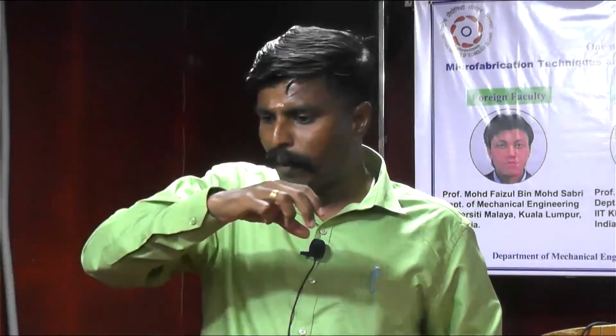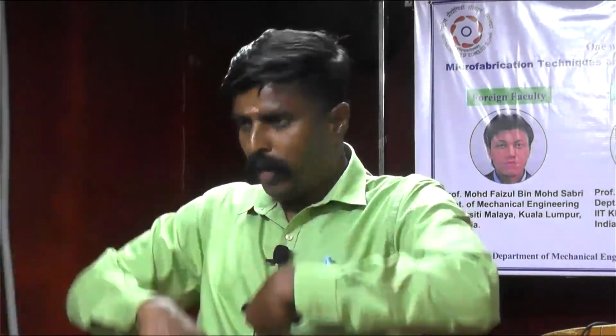There, what do we do before starting the welding process? An in-house fabricated flux is put. Without flux, if you do the welding, the heat conduction will go this way. But if you apply the flux, the conduction will go this way. That means reversal of Marangoni convection. That phenomenon is called reversal of Marangoni convection, because of the surface tension of the flux element you are coating, the flow goes the opposite way.